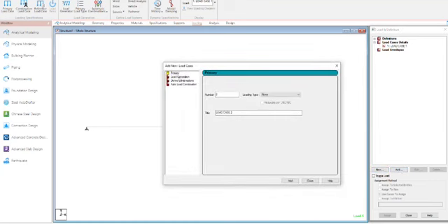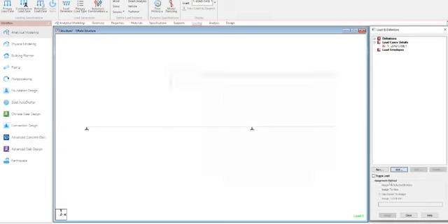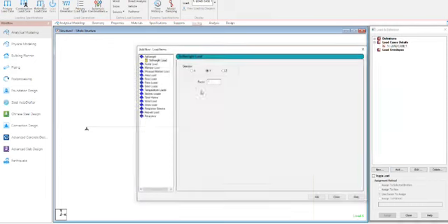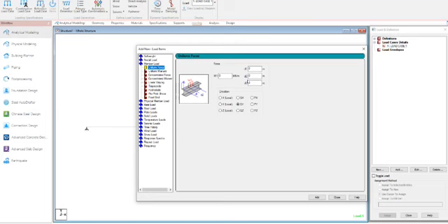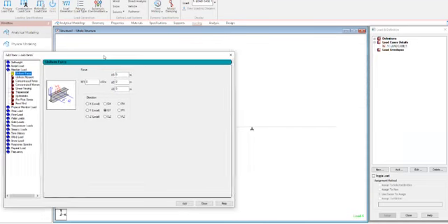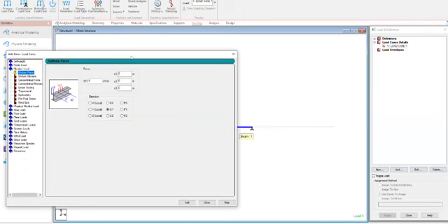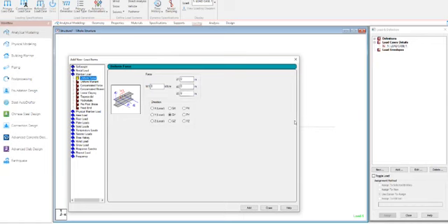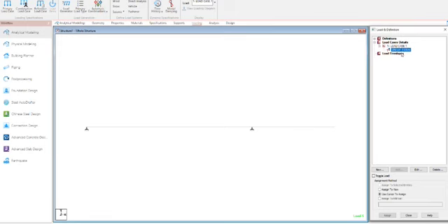So here in this one we are going to add a load case of UDL on the member. So we will put member. We will take this AB 5 meter is there, right? That 5 meter we will apply here in the W1, right? It is showing W1 kilonewton Y direction minus. We will put it 1 kilonewton per meter itself. We will add this load to here, and then here at least we will apply equivalent, means half. If you apply these 2 loads will be equal.